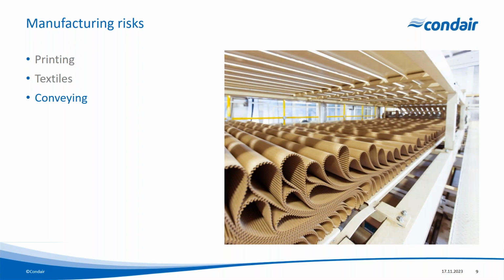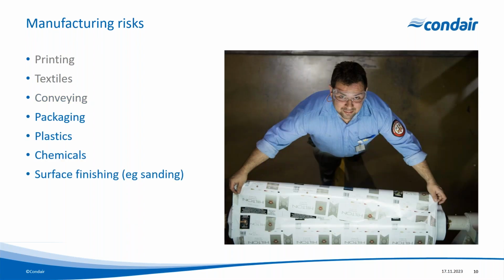And this contact and separation, again, can lead to a static buildup. And depending on the materials involved, that could be either positive or negative. And of course, the effect of that is that we get attraction and repulsion, and we also get the potential for a static discharge. So certainly in a conveyor application, if you've got counters or switches or sensors, that can have an effect on the efficiency of that.